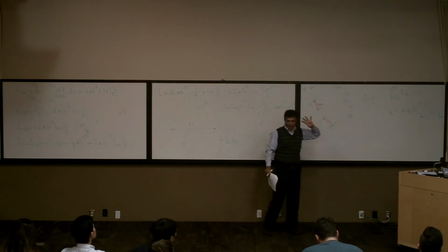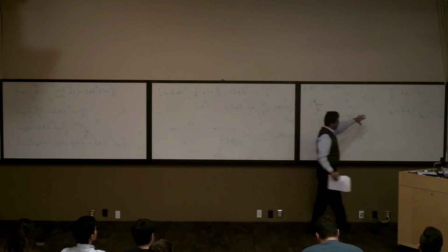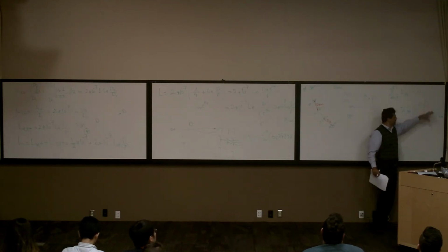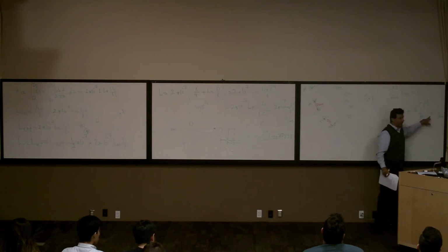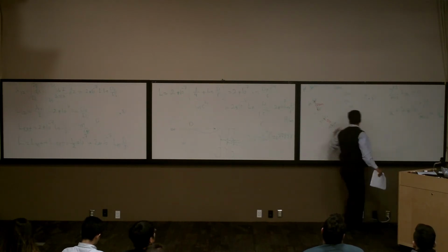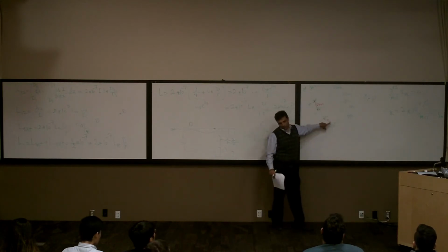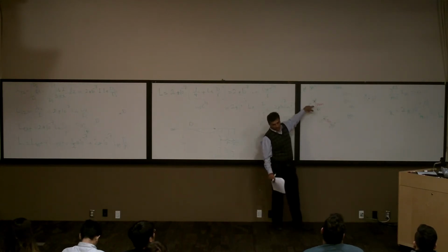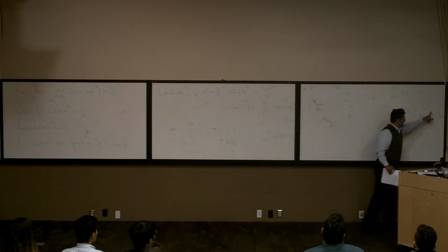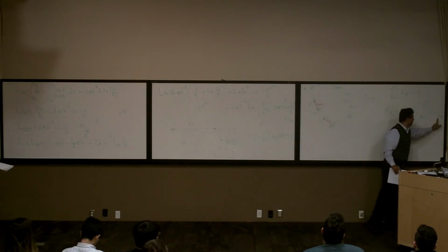Can you read it here? I said 2 times 10 to the power of minus 7, sum from n equal to 1 to N, because I have N conductors. I'm going to go one by one. When n is 1, it's going to be I1, this one. When n is 2, it's going to be I2, I3, I4, all the way, times ln of 1 over dkn.